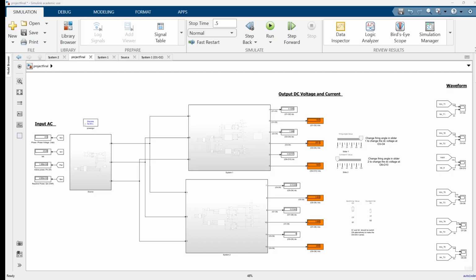Now moving forward, let's discuss the design architecture. To meet these requirements efficiently, a modular converter architecture is used. The system consists of two 3-phase step-up transformers. It consists of a combination of uncontrolled diode bridge and SCR-controlled rectifiers. Then dedicated transformer windings were given to achieve the galvanic isolation.